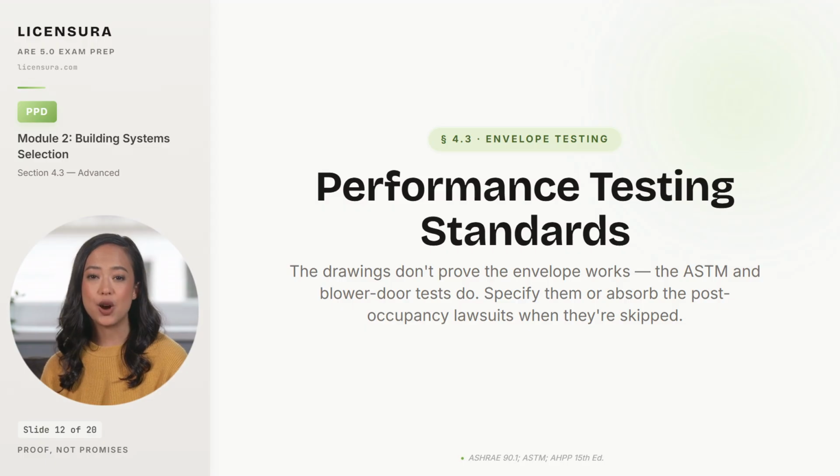Every architect should walk into design development knowing that the envelope is not certified by the drawings. It is certified by tests. Air leakage tests, water penetration tests, structural wind pressure tests, and whole building blower door tests are the only evidence a court will accept that the envelope you designed actually performs.